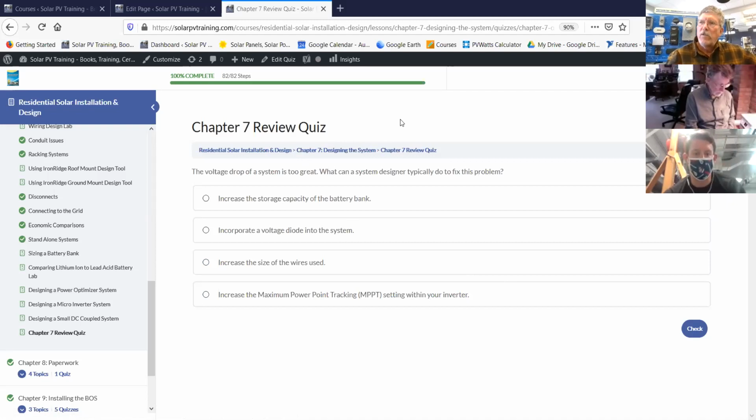And it does mention in the textbook too, there is a provision within the National Electrical Code that says you can use that factor table for calculating the impact for lower temperatures, but only if you do not have access to the specification sheet of the panel itself. So there is sort of a fudge factor way of doing it. But in the world of today with internet access, there's really almost no case where you cannot just simply look up a spec sheet on a solar panel. So even though that table still exists in the NEC, it's almost never used because a good electrical inspector would not allow you to use it.